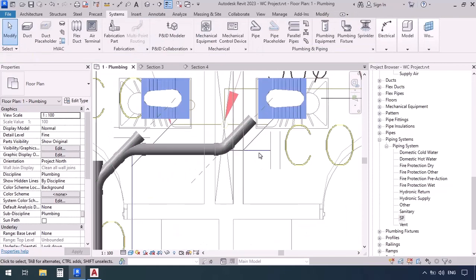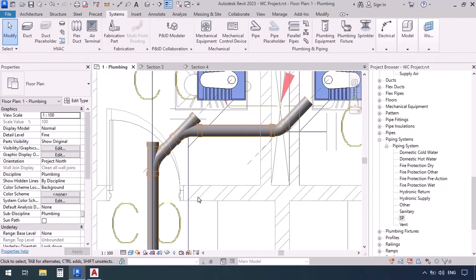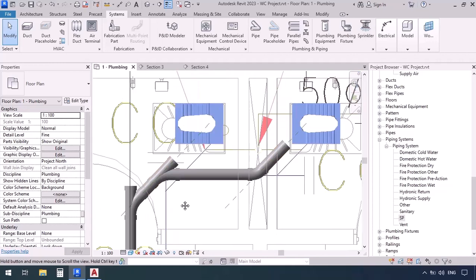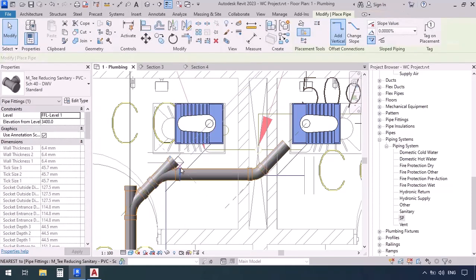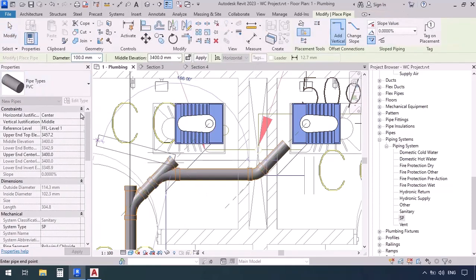So now, do you remember where the plan was and where we've drawn right now? This is the thing with drain systems. The thing which has been drawn in the plan doesn't necessarily completely apply to the result. Now we're going to right click on the T and draw pipe. Now check again, PVC, SP, size is correct and the elevation is inherited by clicking. Only that we're getting close to the fixture, so our slope is supposed to be up.